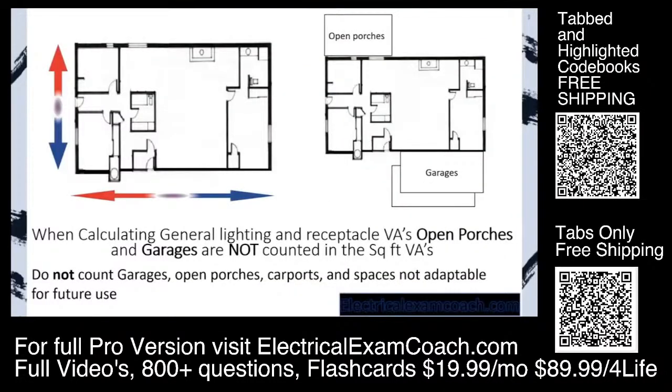When calculating our general lighting and receptacle VAs, open porches and garages are not counted in our general square foot VAs. We do not count garages, open porches, carports, and spaces that are not adaptable for future use.